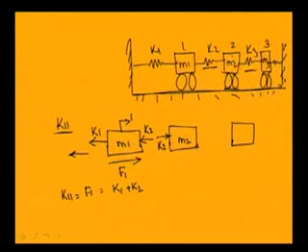Due to this force, the mass should move towards the right, but to prevent its motion we should apply a force F2 in this direction. This force F2 is the force required at 2 to have unit displacement at 1 and displacement at other places equal to 0.